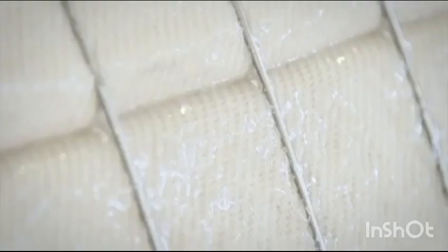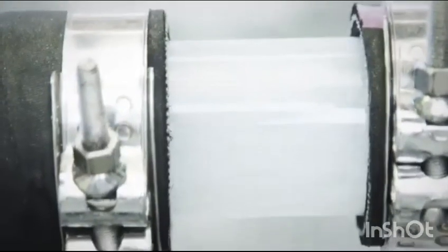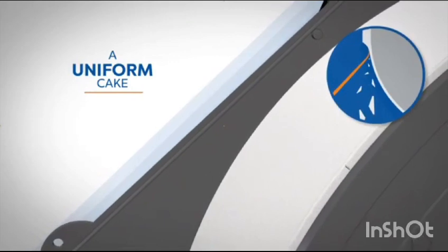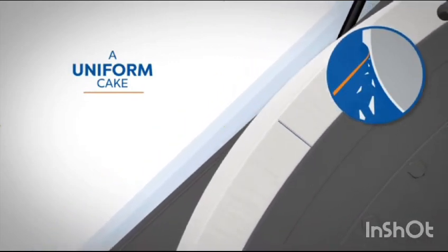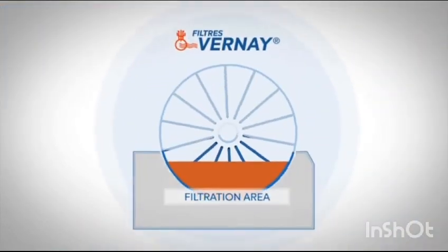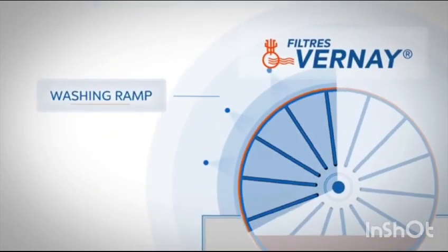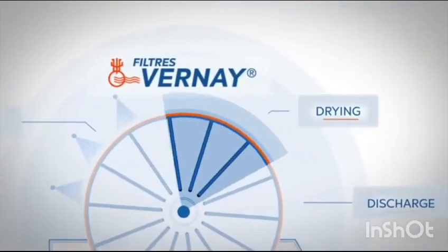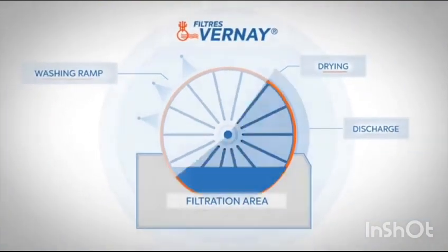The solid phase is retained by the cloth, which is fixed on the drum, while the liquid phase passes through the cloth into the drum and toward the distributor to form a cake, whose thickness can go up to 80 millimeters. During the rotation, the formed cake then leaves the immersed part of the trough to successively undergo a washing operation, followed by a drying operation, which reduces the humidity of the cake just before the discharge. After that, the cake is removed from the cloth by one of our various cake discharge methods.